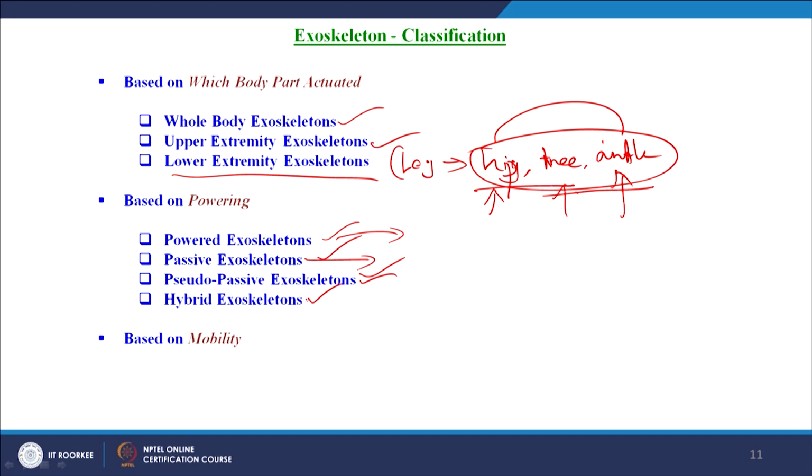And now, finally, coming to the hybrid exoskeletons, they do have all the controllers and sensors of a powered exoskeleton, but they use the functional electrical stimulation technique of the muscles as actuators. This functional electrical stimulation of the muscles means it uses low electric power pulses in order to artificially generate movement of the limbs. That is what is used in the hybrid exoskeletons.